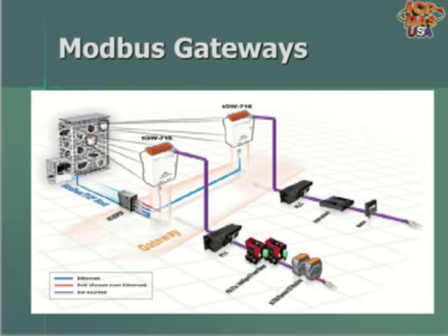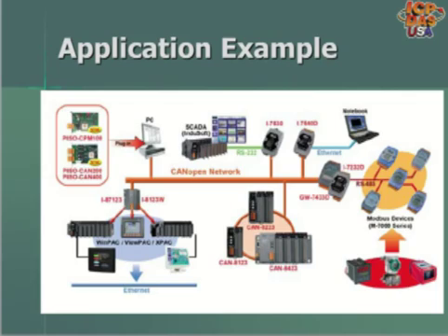Modbus Gateways can be used to convert Modbus RTU to Modbus TCP, so serial-based Modbus devices like power meters, data acquisition modules, and instrumentation equipment can interface with Ethernet-based Modbus TCP systems. CAN communication equipment can allow non-CAN-based devices to communicate over CAN networks. A CAN communication board can be used in PC to provide CAN communication.